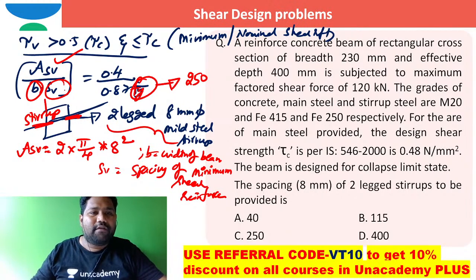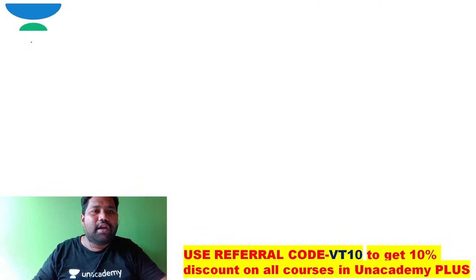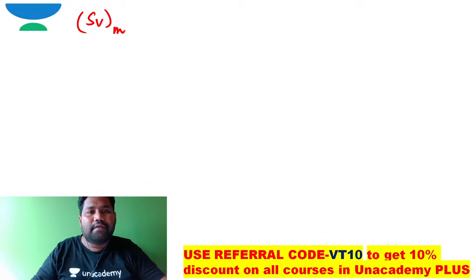So in this case, the one and only unknown is Sv. Asv I know, b is known, Sv I don't know. The spacing of minimum shear reinforcement, that spacing I don't know. So from this equation, I am able to work out the spacing of minimum shear reinforcement.